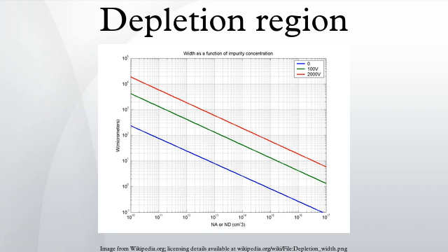Mathematically speaking, charge transfer in semiconductor devices is due both to conduction driven by the electric field and by diffusion. For a P-type region, where holes conduct with electrical conductivity σ and diffuse with diffusion constant D, the net current density is given by J = σE − qD dp/dx, with q the elementary charge and p the hole density.